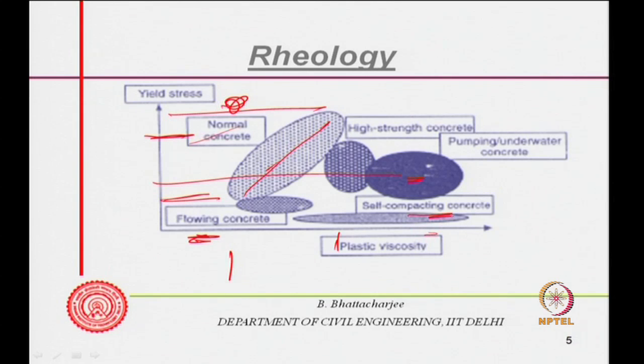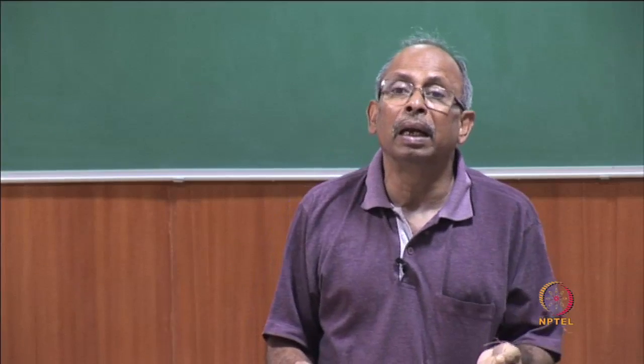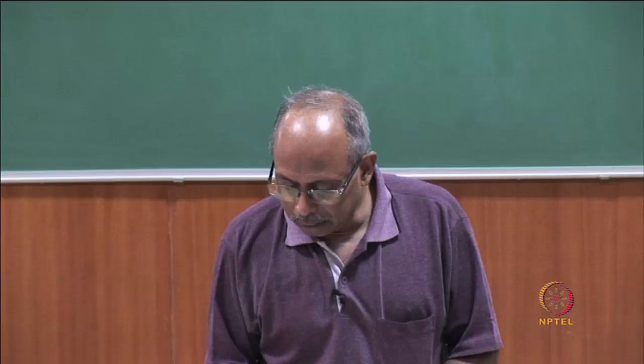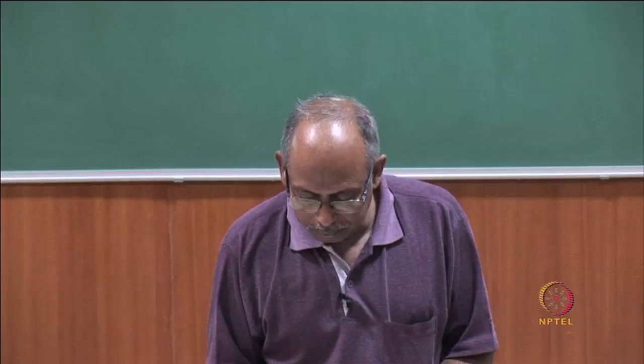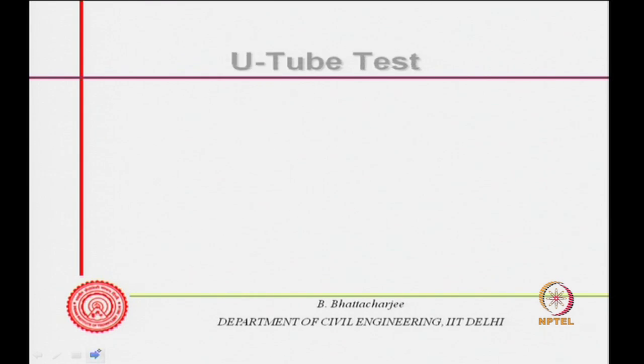Self compacting concrete is somewhere here, flowing concrete, with very little yield shear stress and viscosity ranging from here to there. So, in the rheological scenario, self compacting concrete should have very little yield shear stress and should flow straight away.